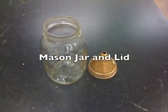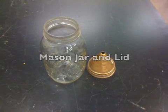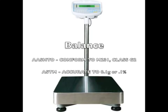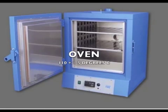To perform the specific gravity test, we will need a mason jar and lid. A balance. For AASHTO, this balance shall meet classification M231 Class G2, while for ASTM it must be accurate to 0.1 gram or 0.1% of the sample mass. And finally, an oven with a range of 110 degrees plus or minus 5 degrees Celsius.